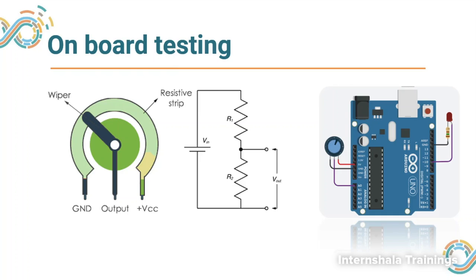A potentiometer is a 3-terminal device which is basically a series combination of two resistors. So that means we get 3 terminals. The extreme ends are connected to ground and VCC. That means the voltage between those 2 points will remain constant as 0 and 5 volt if you are giving VCC as 5 volt. The central pin is the voltage divided output of these two resistors.